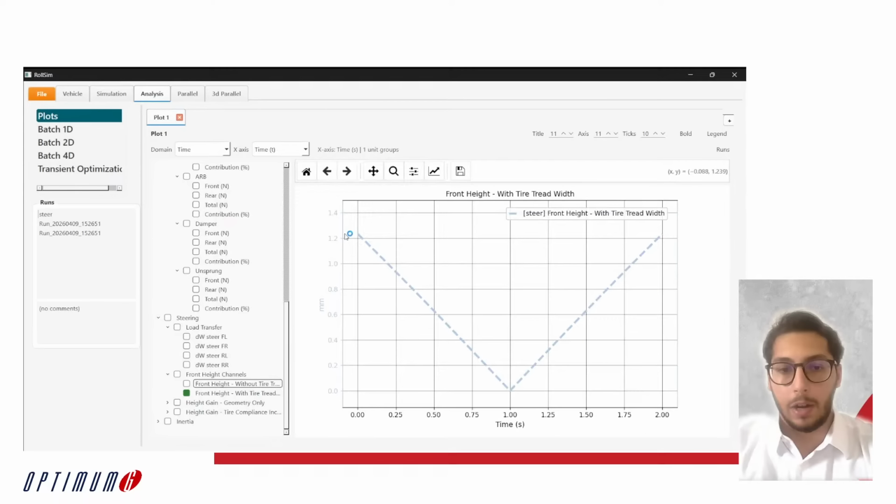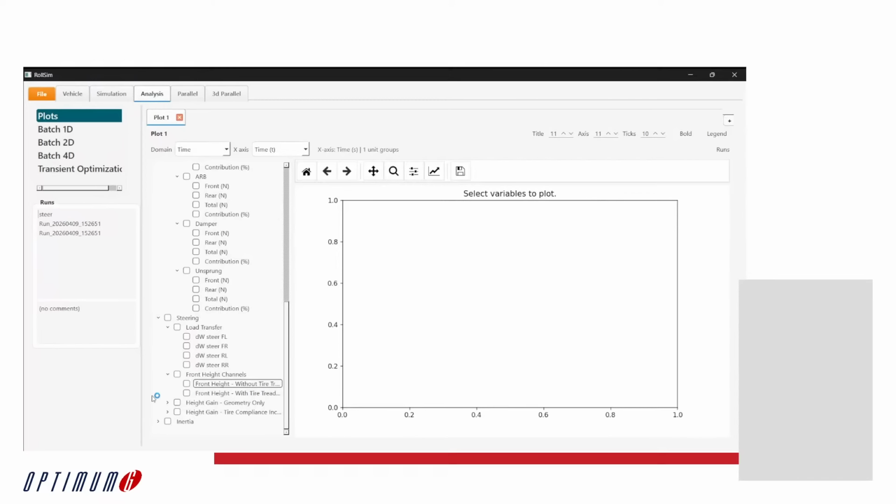we can see that our car lifts up by 1.2 millimeters, or something like that. And it's very important too, because when you're making a turn and you have your aero package, this changes your location in your aero package, balance, etc.